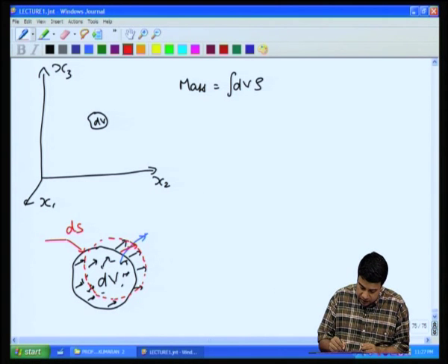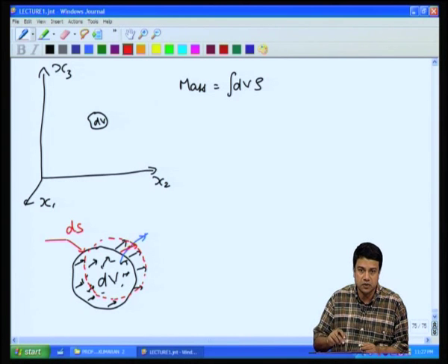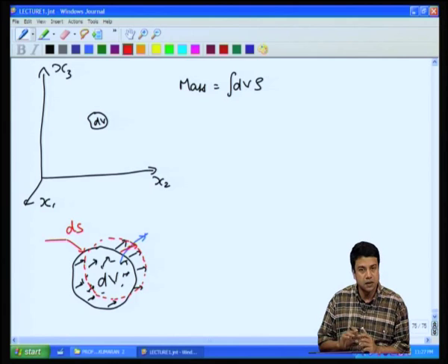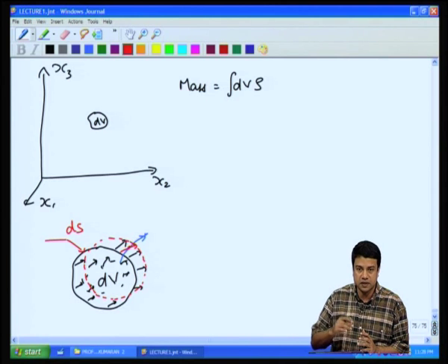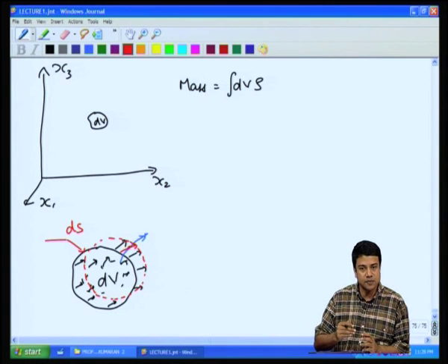This crossing of trajectories is not permitted, because at that particular location it implies that the velocity has two values, whereas we have defined the velocity vector as a single valued function in space. Therefore, fluid points cannot cross from inside to outside the surface, because the surface is moving at the mean velocity at that location. Inside is moving at the same mean velocity as the inside points.